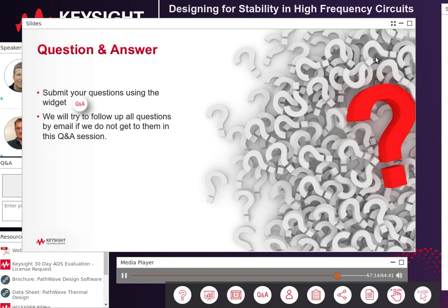So in designs, I track the driving point impedance and the bilateral loop gains together for each probe that's used in the circuit. And for the designer, all this design for stability power can be utilized and optimized against during the performance and design optimization phase of their circuit design, not after the circuit's been designed or completed, or worse yet, when it gets to the lab and it starts oscillating.